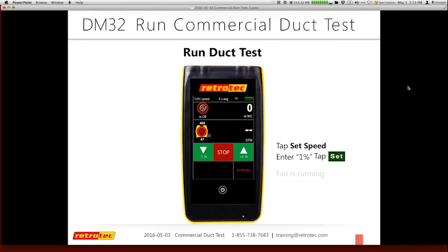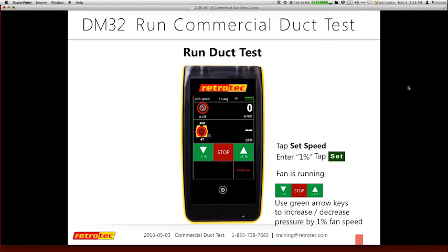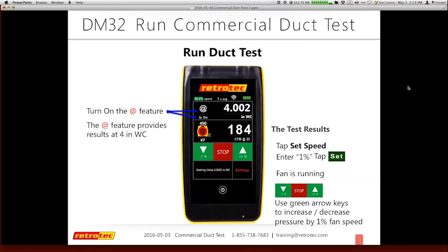So, Joe, yes, sure. There's 2 points to be made there. One is that if you're trying to test at 4.000 inches of water, you're never going to be exactly there. You're going to be slightly above, slightly below, and so on. And even if you do an averaging and you can measure it very accurately at 3.9 or something, then you have to make a correction back to 4.